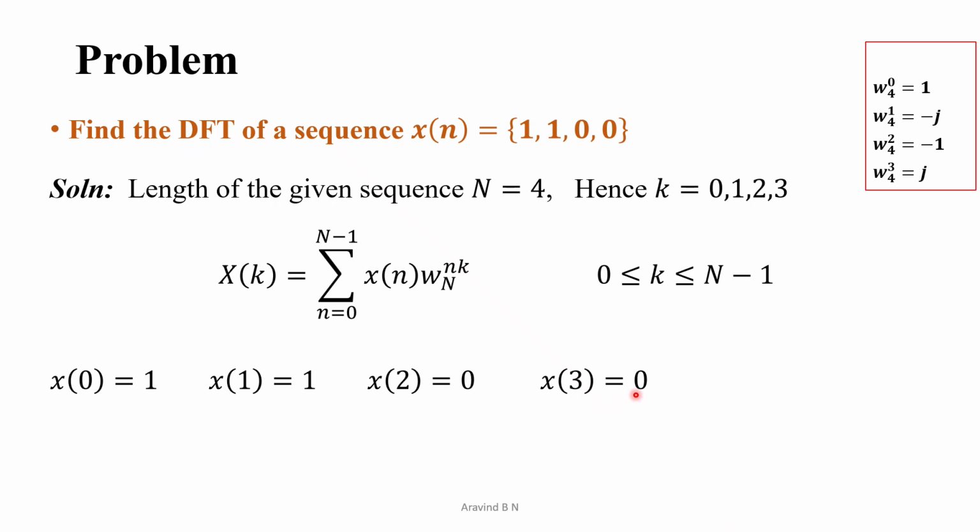So this is the basic understanding of a very simple DFT problem that you have to make. Without understanding this, it will be quite difficult to arrive at the solution. So whatever is given as data, we must know what it actually is. These are not simple numbers. These are the amplitude values of the signal at those particular locations, location 0, 1, 2, 3.